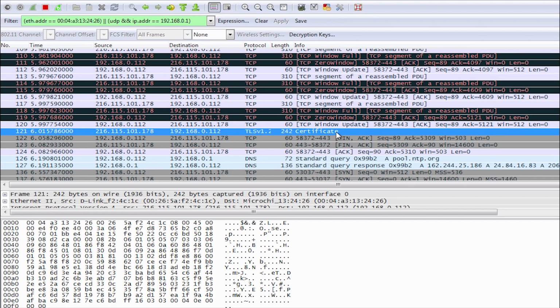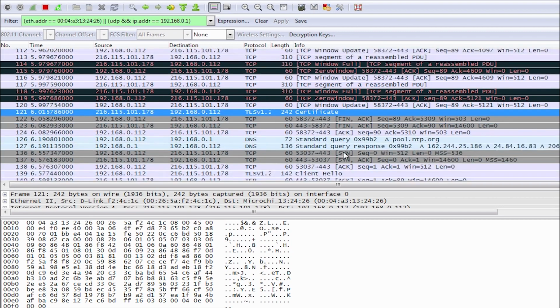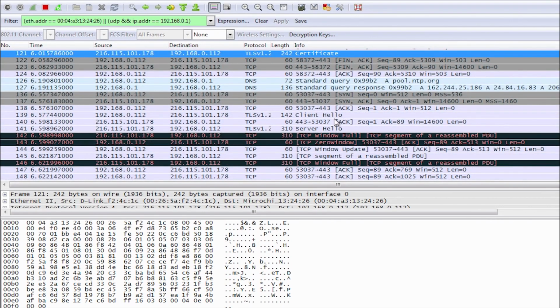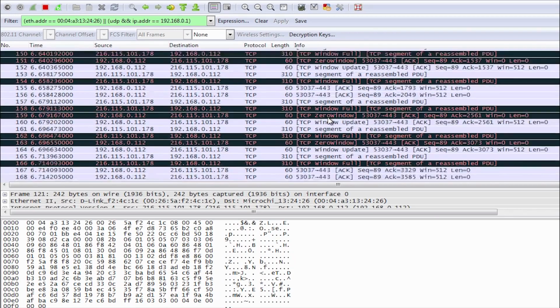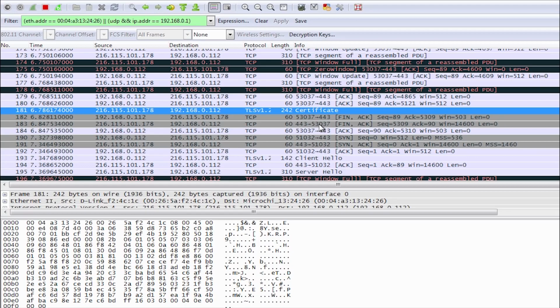The reason is that the SSL library is unable to validate that certificate because the time has not been updated onto the application yet. So it rejects that certificate because the issue date and expiration date do not match the date on the TCP/IP stack. If I keep scrolling down, there's another connection being attempted. Here's the certificate, and here's the socket again being closed.